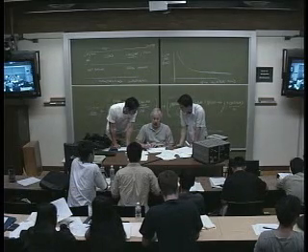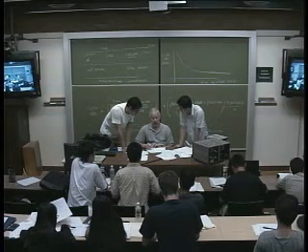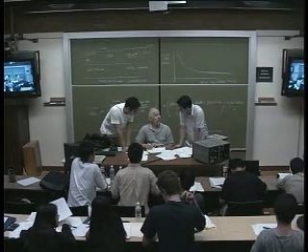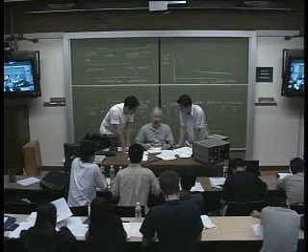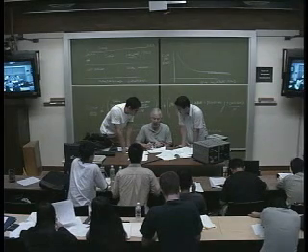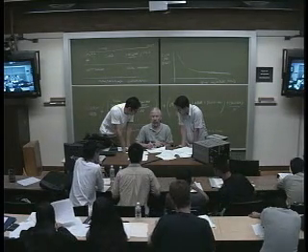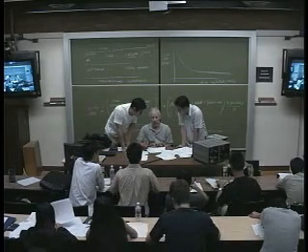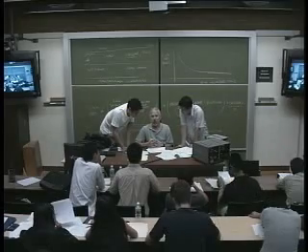Yeah. This sets the high swing, but I've got to somehow make sure this transistor is in saturation. So it would go out of saturation? Potentially could, pretty easily, because this is a very high gain node right now, right? There's some mismatch of currents here and currents here that would be setting the voltage on this node.